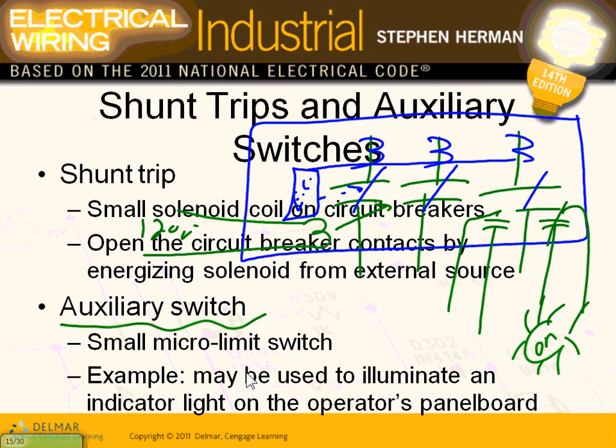Now we're starting to talk about control, exactly like that control on the wall. Like a magnetic starter, remember with the magnetic starters we did, all have auxiliary contacts so that you can take a signal in and out of the circuit breaker to interface it with other things.